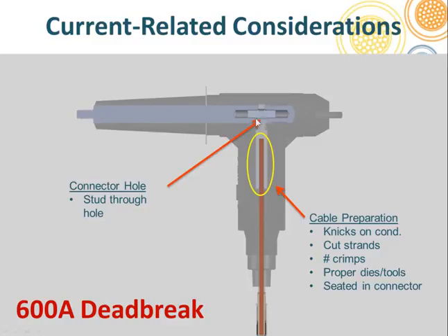What happens is he ends up pinching the top of the connector right here. He torques it, everything seems good, and everything is good for a while. It will carry current, but as soon as he starts getting any mechanical movement, through thermal cycling, through faults, anything else, it will work its way out and eventually fail.